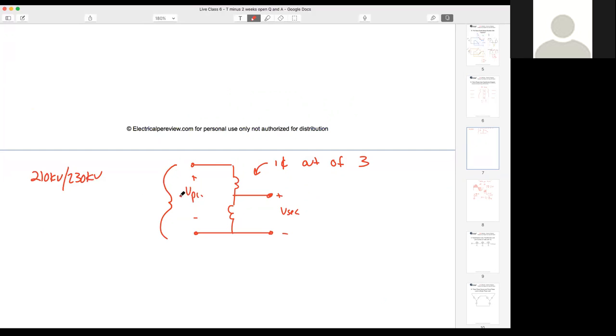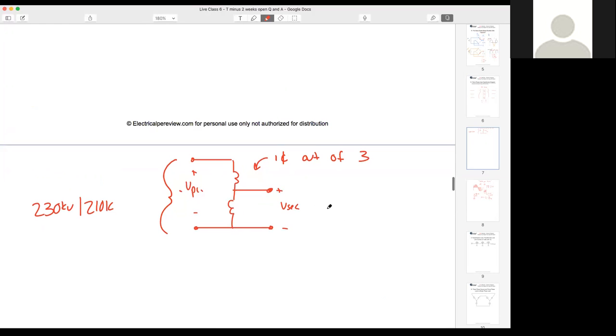these actually might be flipped around. You caught me. Let's say we're regulating it down from 330 kV to 210. Sorry. Just for the sake of this problem, because I drew it backwards, I'm used to drawing it like this. How do we know that this side is going to have higher voltage? Because there's more windings. Your winding ratio corresponds to your voltage ratio, since you've got the sum of both windings on a primary side and just a common winding on the secondary side. The secondary side would have to be smaller.